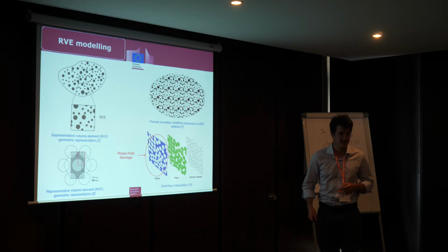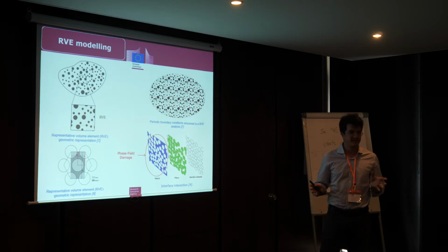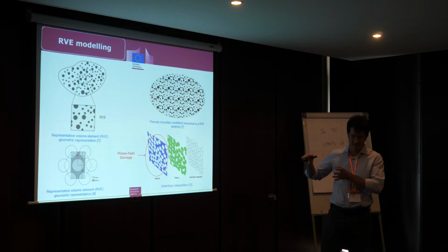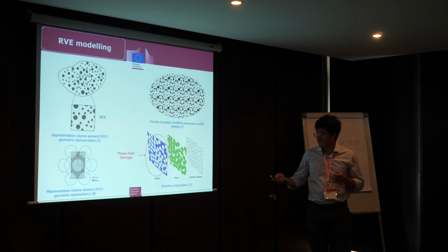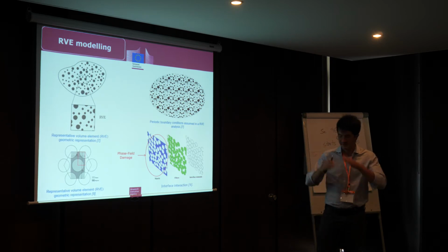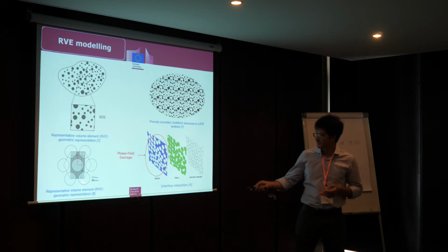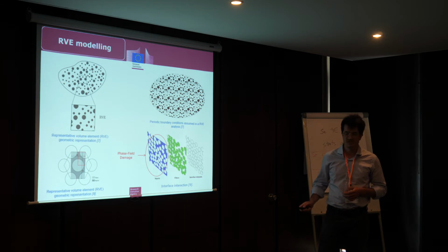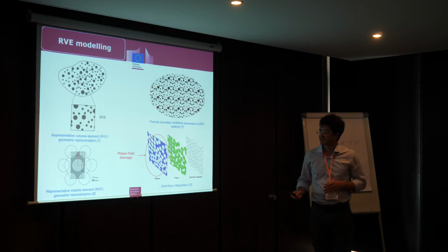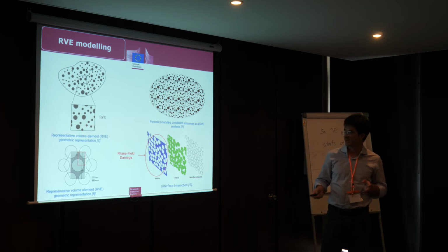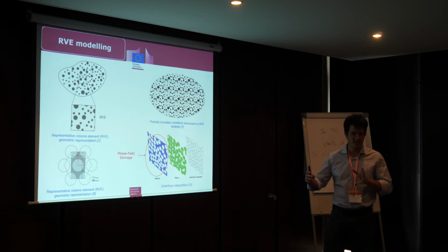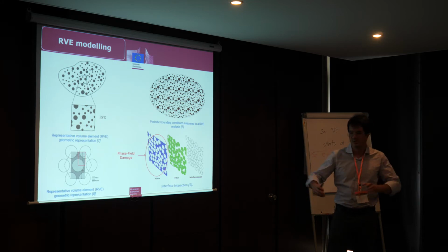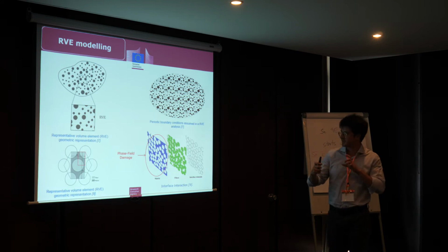So an RVE is assumed as a representative section of a general homogeneous or not homogeneous material. Depending on the authors, there are many people who assume a very specific arrangement of fibers, like the one we see here. But in general, most people prefer to use this. So the problem with this approach is whatever you consider is random inside this RVE, because when you actually model, you assume your continuum is actually a repetition. So what is not homogeneous is contained in that specific volume.